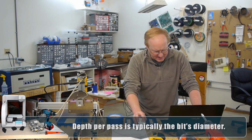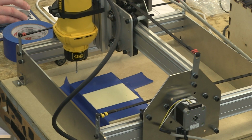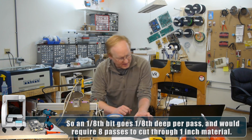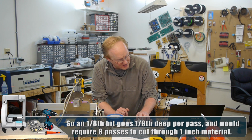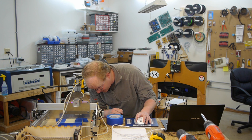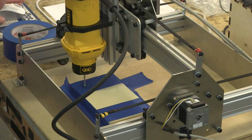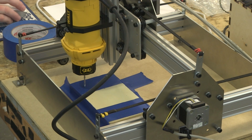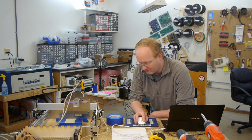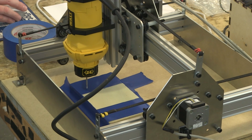So I'm going to set a Z0 position in this block of foam. There is an electrical plate we can use to complete a circuit between the bit and a plate to set the Z depth, but we're having some noise issues with this unit, so I'm just going to do it manually. When we generated the G-code, we said that the top of the material was 0, so that's what I'm going to do here. That looks pretty good. Maybe just up a hair. Okay, I guess we can check by moving other things around and see if it scrapes the tape. That looks pretty good.